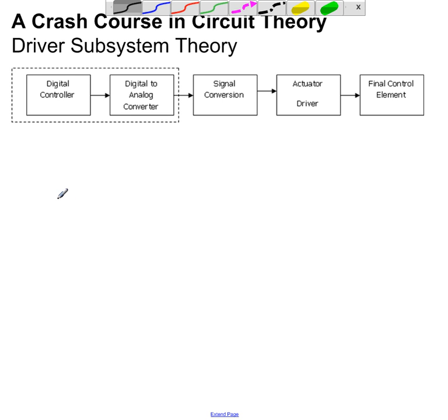The idea behind the transistor driver is simple. Use the transistor as a current gain device, and using the transistor as a current gain device, we're allowed to take a small current and use it to control a much larger current. And the current limit is dependent upon the capacity of the transistor.